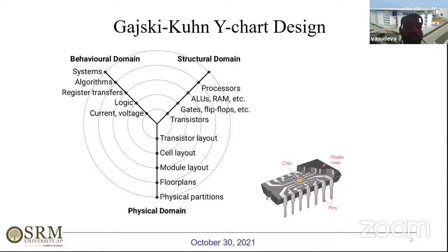The behavioral domain focuses more on algorithms and system design. The structural domain focuses on structure and logical design. Transistor level design focuses on NMOS, PMOS, and CMOS structures, and the layout design targets the back-end design completely. The entire structure gives the foundry the information for